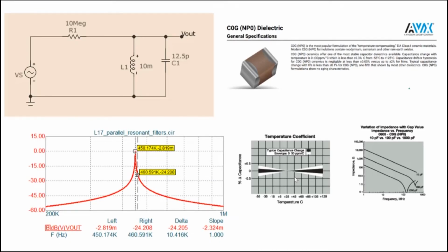Okay. Now, resonant frequency is very important for us, and if you're trying to pass a 450 kilohertz signal and you've designed an L and a C such that it's tuned to 450 kilohertz, you want to catch this particular radio channel. The problem is that L and C, if I take typical inductors and capacitors, have problems of tolerance. So you may pick a capacitor which is labeled as 12.5 picofarad, but when you exactly measure it, you'll find that because of tolerances it's maybe 10%, 20% higher.